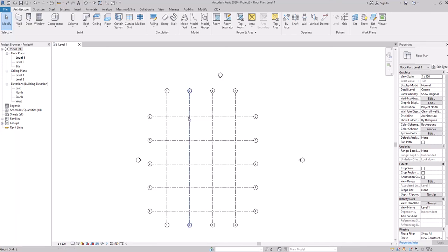When you open an architectural template in Revit, you will already be given these two levels here. The levels that you add in the software itself will help you a lot in terms of the walls, the flooring, and everything else. You can constrain the walls to the levels, and then even if you change the level height, all of the walls will change automatically, and so on.